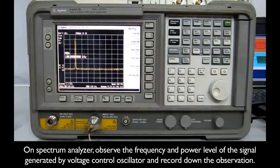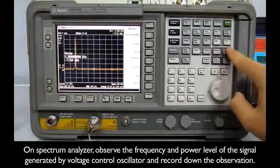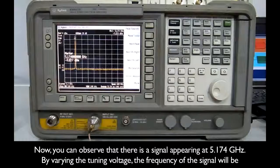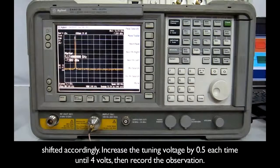On the spectrum analyzer, observe the frequency and power level of the signal generated by the voltage control oscillator and record down the observation. Now, you can observe that there is a signal appearing at 5.174 GHz. By varying the tuning voltage, the frequency of the signal will be shifted accordingly. Increase the tuning voltage by 0.5 each time until 4 volts, then record the observation.